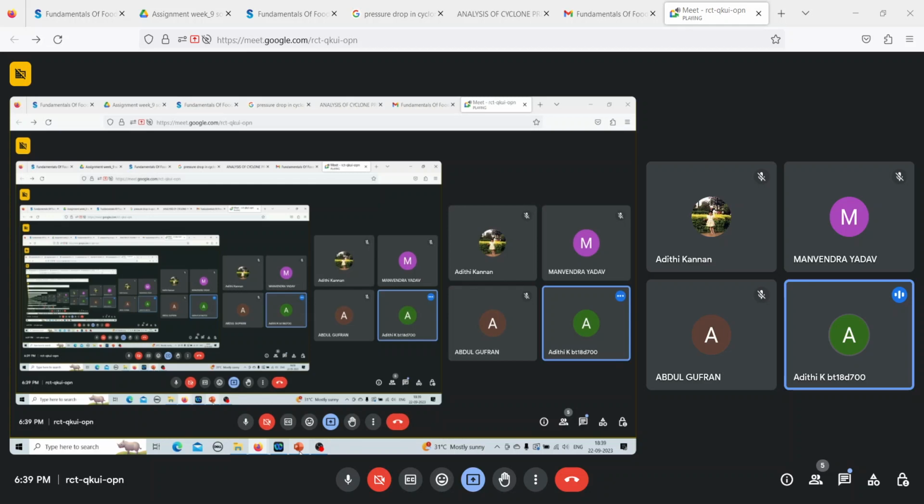A spiral separator is made up of inner spiral flights and outer spiral flights. The round materials roll down faster than the materials with irregular shape, and the orbit of the round materials, the radius at which it goes out in a spiral manner, will keep increasing as the velocity increases, till it falls off from the inner flight to the outer flight, hence resulting in separation.